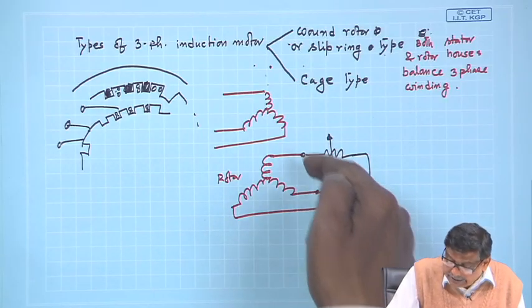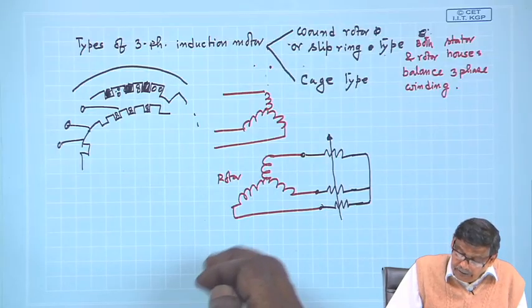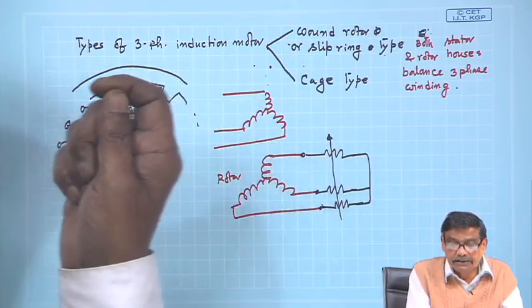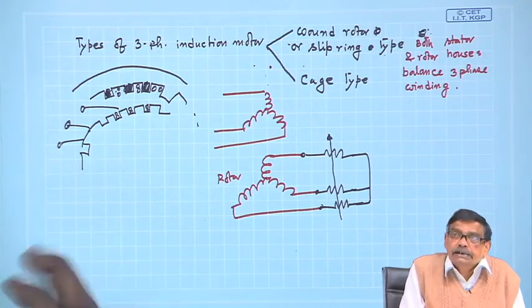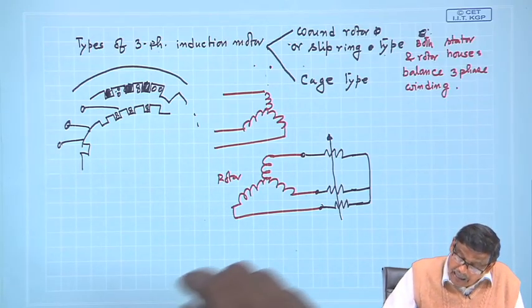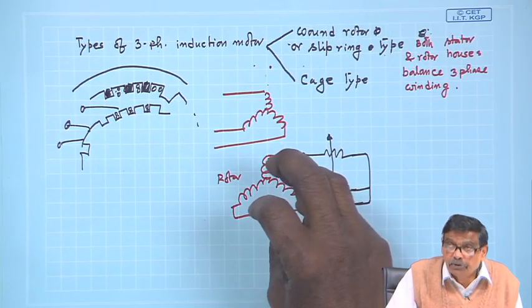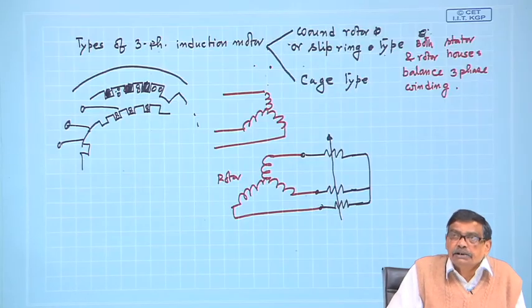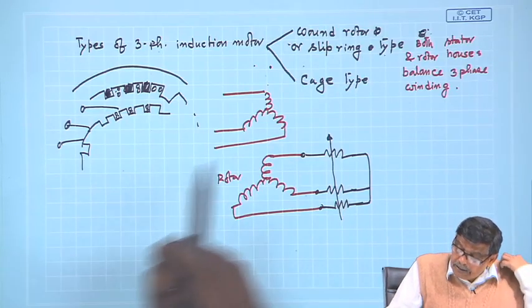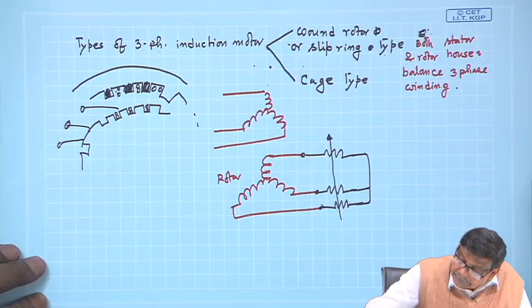Therefore, to access the rotor terminals properly, it cannot be that the rotor terminals are there and I will just connect resistance. There must be some intermediary things which will make these 3 terminals, which will be rotating, appear stationary to the user of the motor, so that he can connect the resistance comfortably. Okay. So, how can this be done? It can be done very nicely like this.